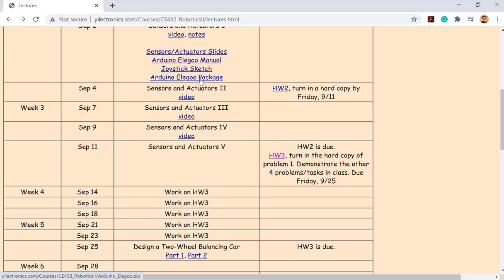There's a folder called code, which has all the sketch examples you can directly use. They're ready to use, and they have libraries. If you do not have the libraries loaded in your Arduino IDE, you probably want to copy and paste that library to your Arduino folder on your desktop or laptop to make it work.